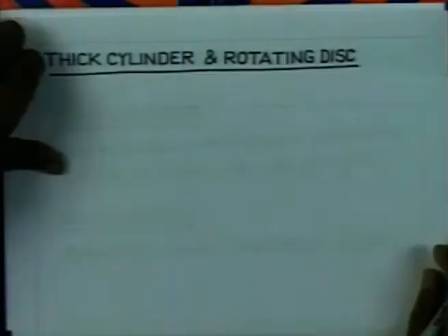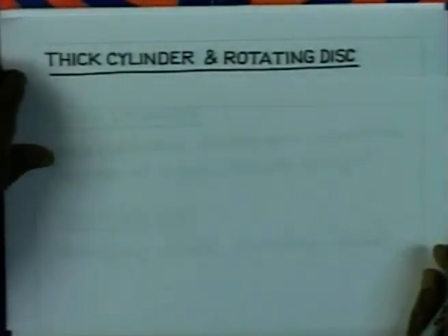Let us now consider determination of stresses in thick cylinder and rotating disc. You are already acquainted with the stresses in thin cylinder. When the thickness divided by the internal radius of a cylinder is less than about 0.1, it is called thin cylinder.